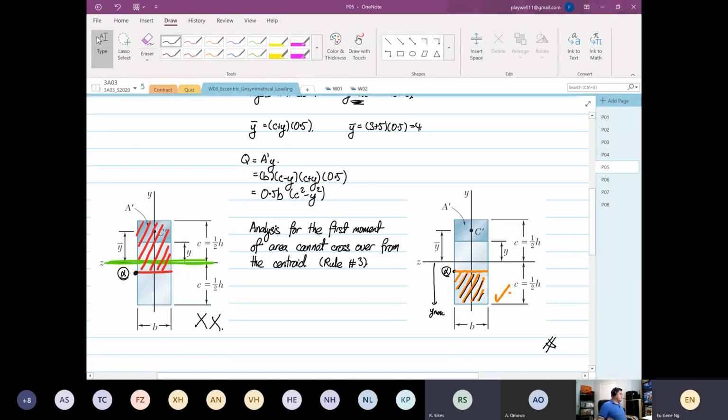Right? Yep. So that's why your Y is a variable. We are going to calculate the distribution. Likewise, we did our distribution calculation based on bending moment. Bending moment, we're also calculating the what? The distribution, right? Because stress is equal to My over I. Your Y is a variable. Likewise, for this, we are looking for the distribution of the shear stress. Okay, good question. Anyone else?